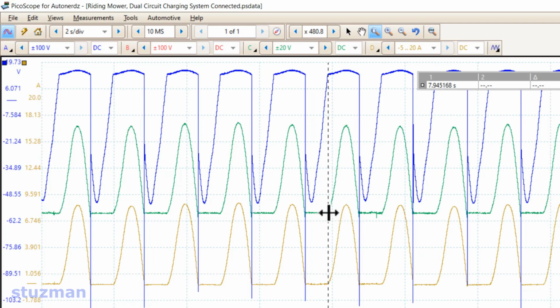Notice how when the diode turns on, it coincides up here with the stator voltage, right in that little corner. Let's take a look at it when it turns off. It turns off right there when this high voltage spike is created, and you notice that it's just this little area right in here that we're utilizing when the diode is turned on.